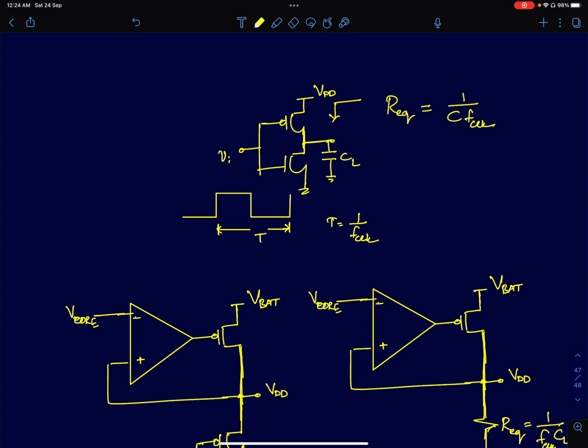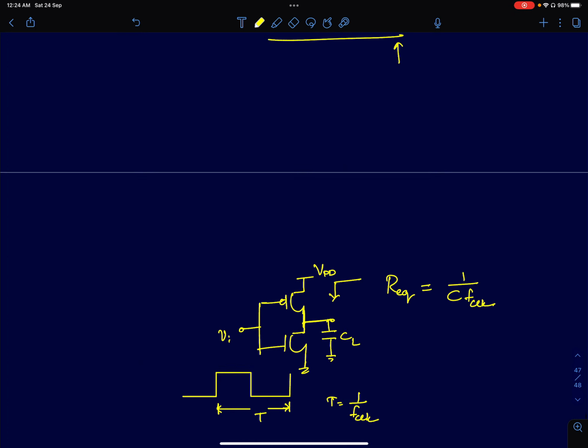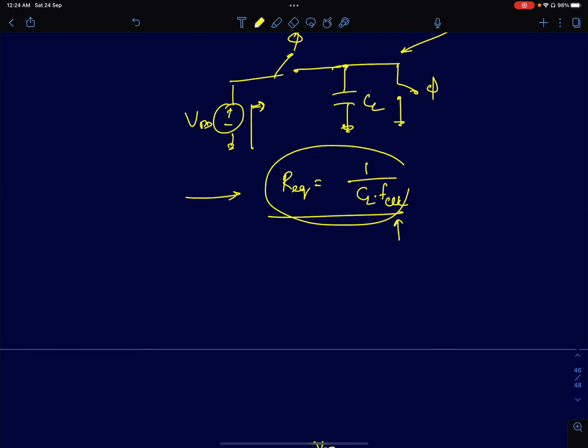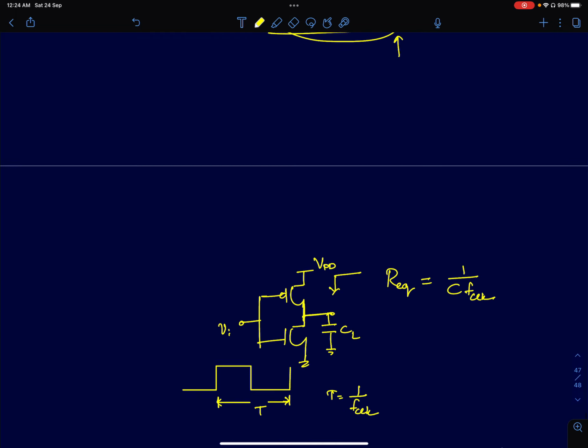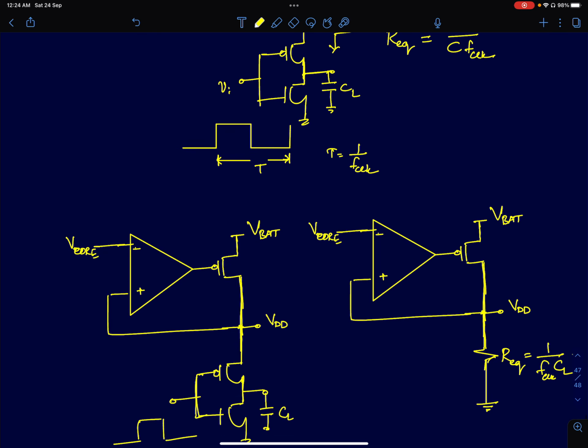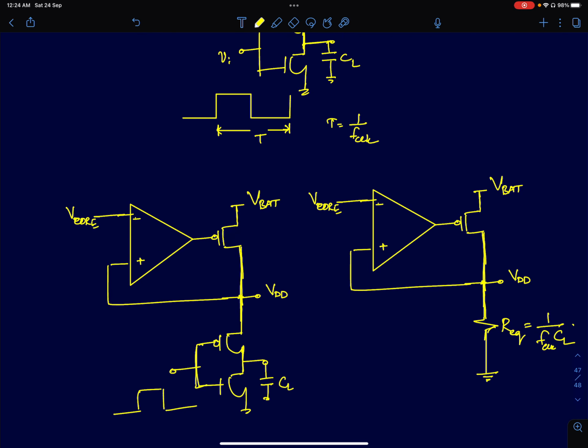Where this equivalent resistance matters to us is especially for analog engineers who are designing, say, voltage regulator circuits. Voltage regulator engineers are mostly dealing with feedback systems, so you are used to analyzing the small signal behavior of this LDO, using terms like phase margin, gain margin, and DC gain.